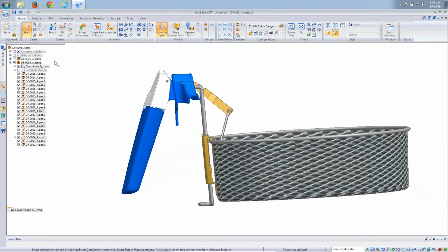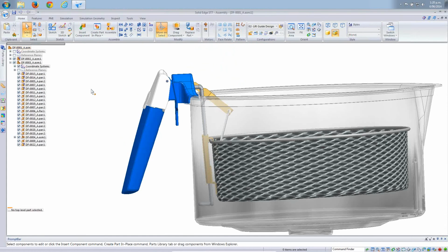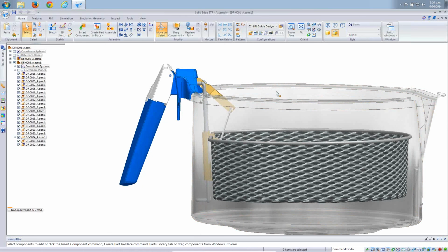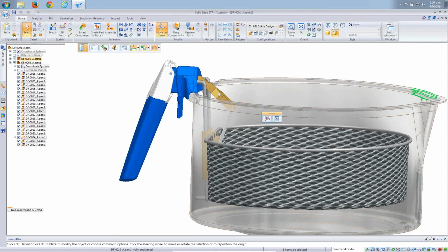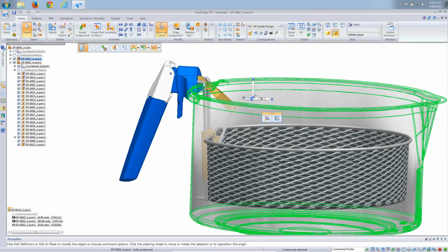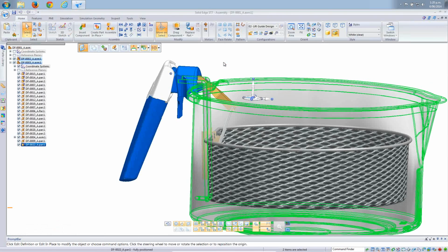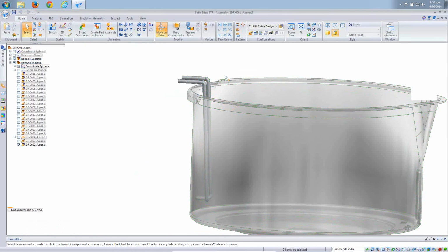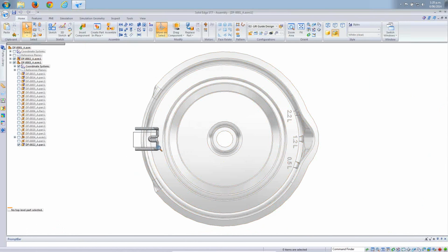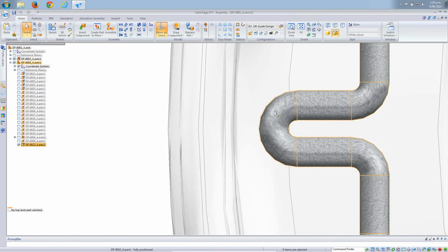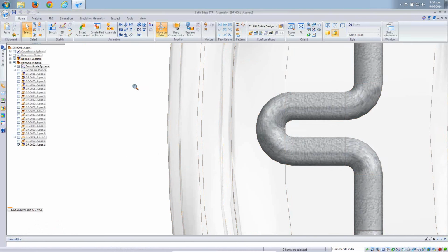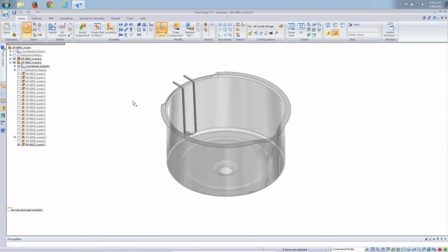Actually, we can head up to the top level assembly as well. We'll show all of the components in this assembly, and what I'd like to do is just to make sure that the component we've just selected really needs to be connected or seated on the inside face of the pan here. So we'll grab those two components, spacebar to change the select filter, do a show only on that. If we change the orientation, we can see if we zoom in here that this piece of the bar isn't seated inside, it isn't tangent to the inside face of the bowl.